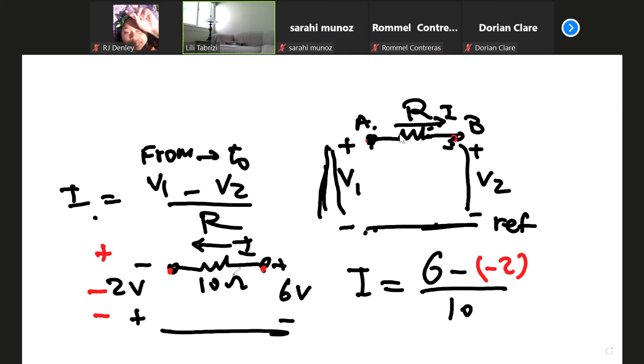Textbooks don't show nodal based on this shortcut. That's why students always remain confused. I cannot make it more systematic than this. So do you always switch polarity? Yes. This is one time that you switch polarity to make sure that the reference has minus, node has plus. Even if you end up with a negative number, that's okay, because you want to use the shortcut.